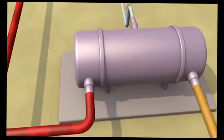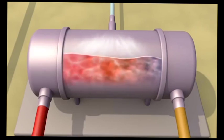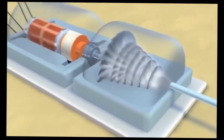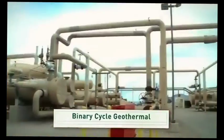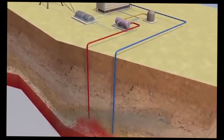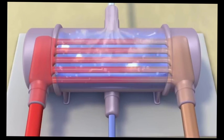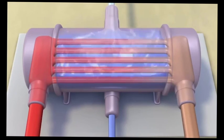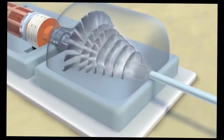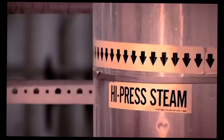Another geothermal technology is called a flash steam power plant. A pump pushes hot fluid into a tank at the surface, where it cools. As it cools, the fluid flashes, or quickly turns into vapor. The vapor then drives a turbine and powers a generator. A binary cycle plant works differently. It uses 2 types of fluid. Hot fluid from underground heats a second fluid, called a heat transfer fluid, in a giant heat exchanger. The second fluid has a much lower boiling point than the first fluid, and so it flashes into vapor at a lower temperature. When the second fluid flashes, it spins a turbine that drives a generator.